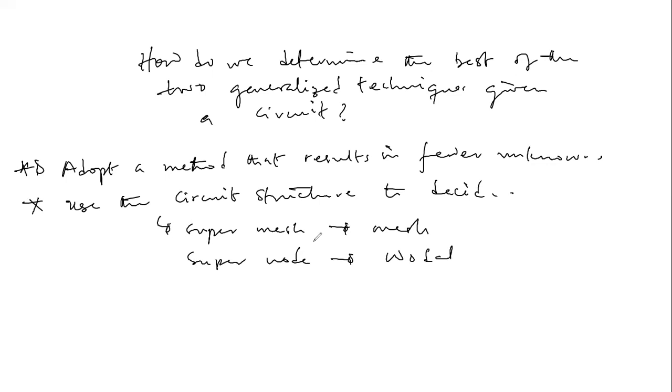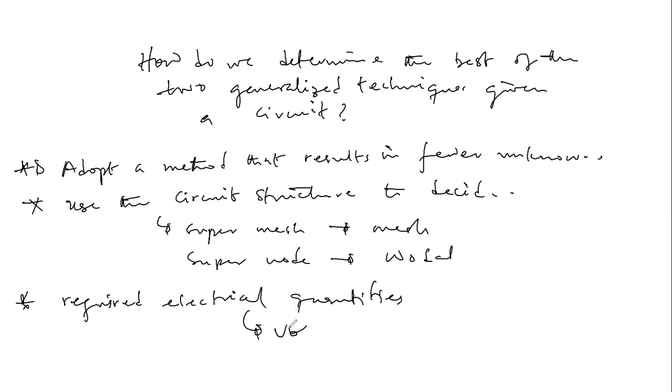Okay? And also, you may want to decide using the required electrical quantities. So if we have to solve for voltage, then I think the nodal technique serves the purpose. And if we have to solve for current, then the mesh analysis may be sufficient.